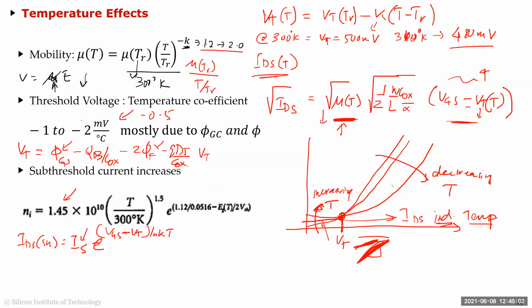When you are a designer, especially an analog designer, you don't need to know the exact terms, because when you're debugging a circuit, let's say I get a chip back and I find out that I have a high temperature problem, just knowing these behaviors will get me on the right track. I'll say, if it is high temperature, it's got to be low VT, it's low mobility, it's probably a mobility issue, or I'm running into some headroom issue. Once you know these behaviors, it'll lead you in the right direction for debugging and designing properly.